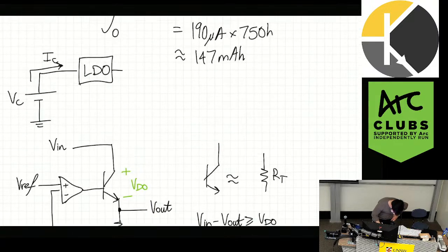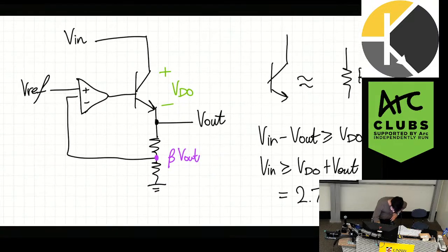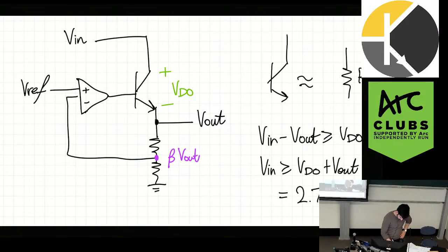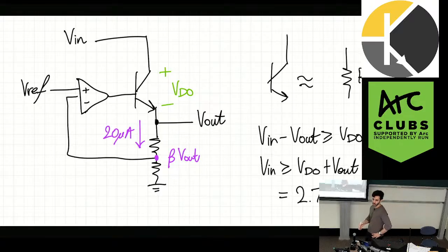If we go back up to this drawing I made, the current it was referring to as the LDO current is this current. That current is 20 microamps, which is non-existent. You can kind of ignore it. I'm just going to include it for the sake of completeness, but you'll see even the final answer is almost nothing. The reason for that is because the op-amp draws no current.